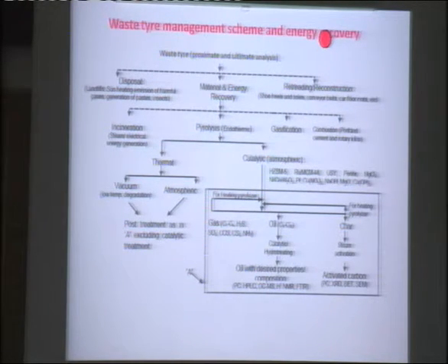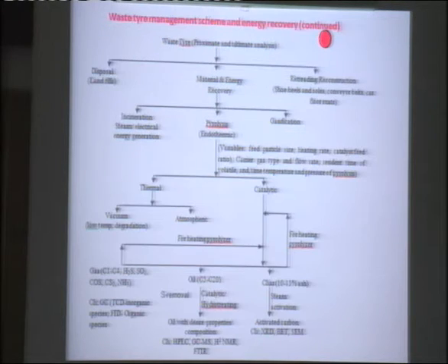You have the pyrolysis reactors, different types of pyrolysis. You can see vacuum pyrolysis. You see shorter residence time reduces undesirable products. The more time you keep the gas inside, the more the polymers and molecules break down and form other things. So you need to reduce the residence time as much as possible. The yield of pyrolysis oil is higher. Operation at lower temperature, you get higher oil. Operation at higher temperature, you get less oil and more gas. Okay, the concentration of aromatics in pyrolysis oil increases. If you use vacuum pyrolysis, you get more aromatics. Aromatics is utilized for gasoline purposes.